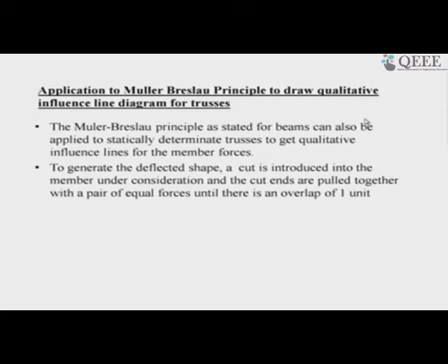Anyway, for the truss, since it is not subjected to bending moment or shear force, but only axial forces, I will destroy the capacity of that particular member to resist the axial force, either in tension or compression, and also try to pull it a certain distance, suppose a unit distance, to see how the configuration changes for the truss, assuming the sections are pinned at the member ends.